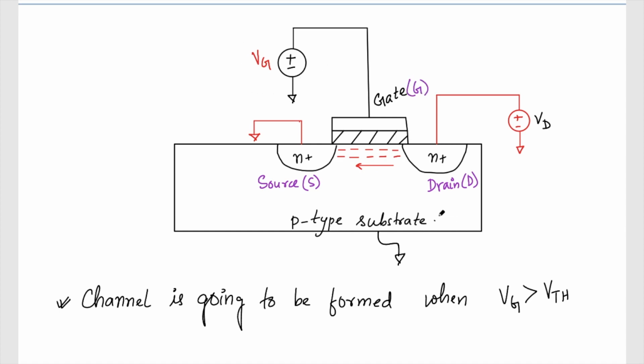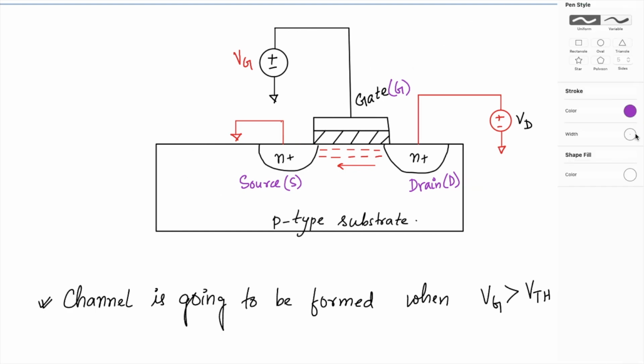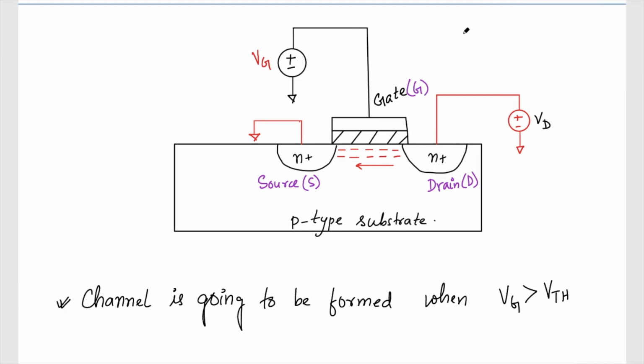Of course we need to ground this whole substrate, or connect it to some potential. We cannot access the back side of the substrate. We access only the top side, and there is going to be a P plus island. So this is the same type, P type.